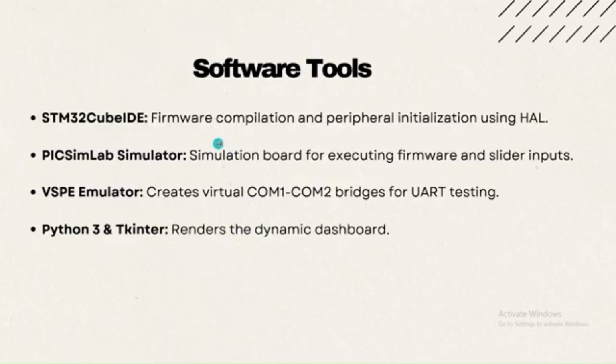And coming to the software tools, here we used STM32CubeIDE to compile the C code firmware, and PICSimLab to simulate the Blue Pill board, and VSPE to create a virtual serial bridge, where I used COM1 and COM2. The dashboard UI was programmed in Python 3 using Tkinter.